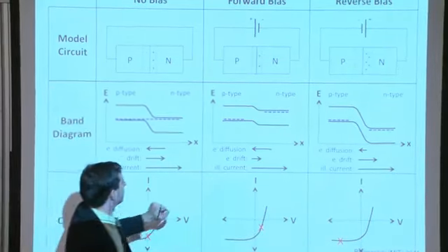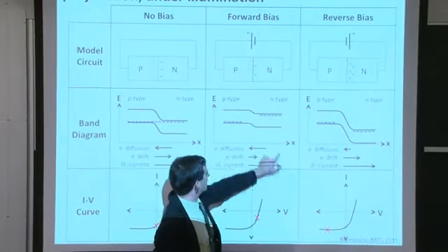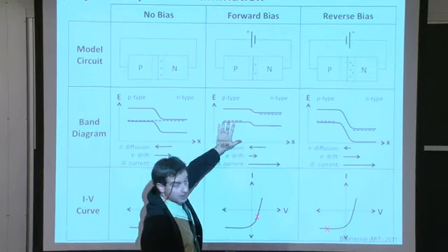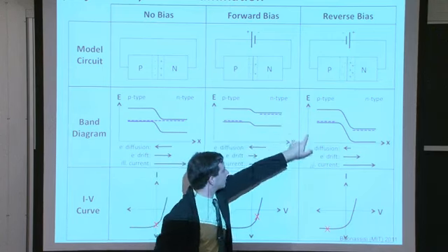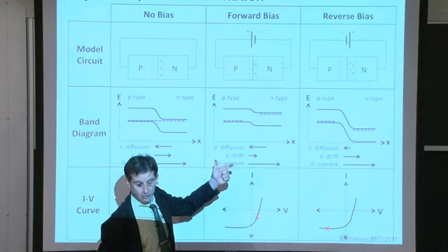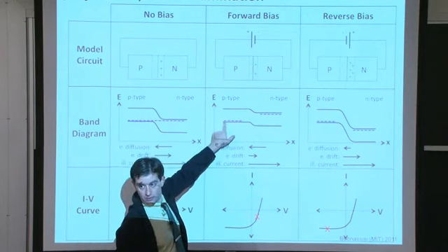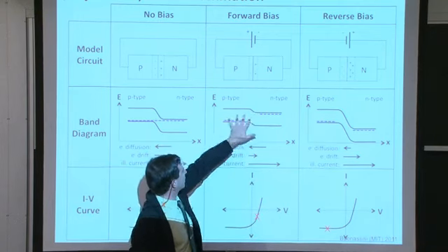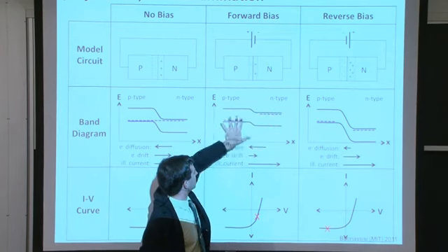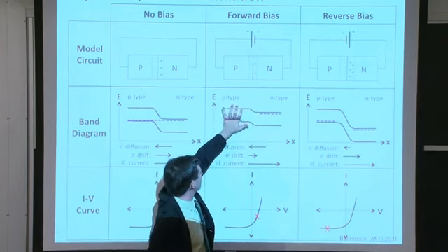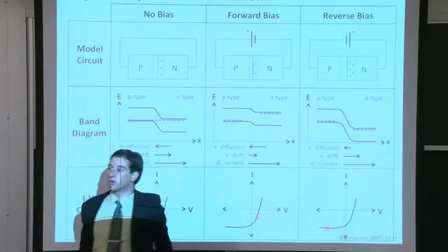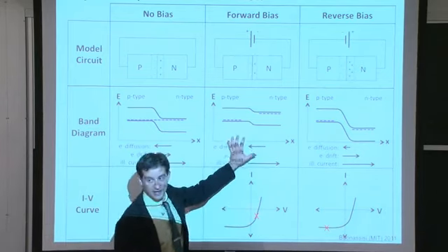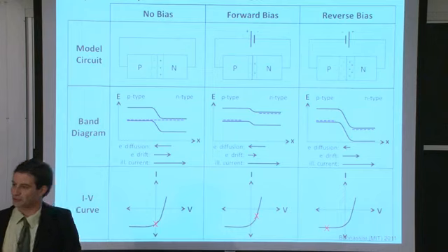Why? Well, first off, the voltage is such that we can power an external load. We have charge separation. The electrons are accumulated over here, and they have higher potential than they do on the other side, which means that there is an incentive for them to go through the external circuit, deposit their power across that external load to get back to this other side where their potential is lower, right? So the voltage is favorable, and the current is also favorable, because now we have light coming in, and this generation current is creating carriers here in the P-type that can then be driven toward the N-type because of the built-in field. So the conditions are just right under illuminated forward bias conditions to drive power through our external load.